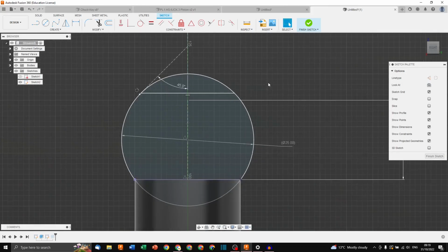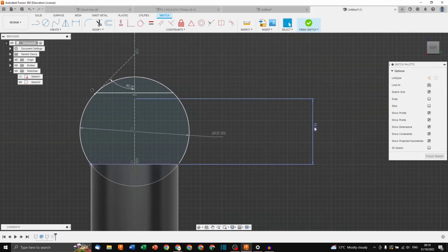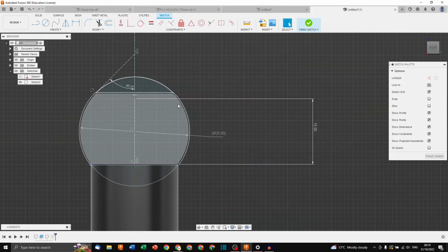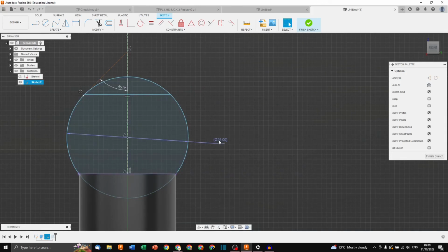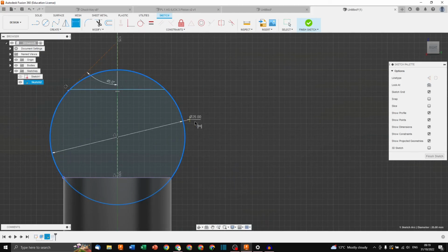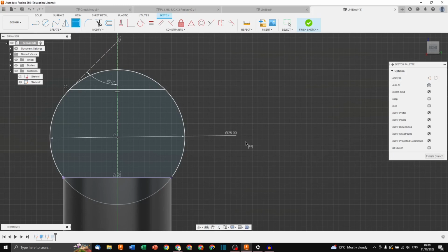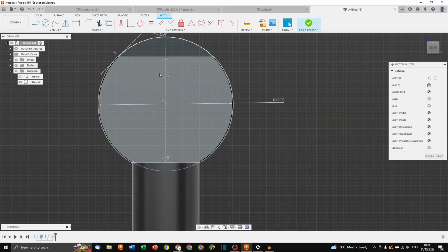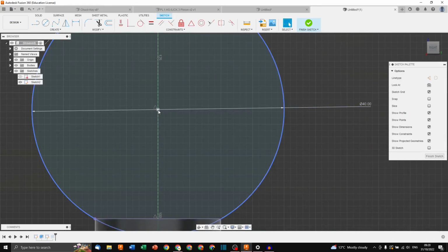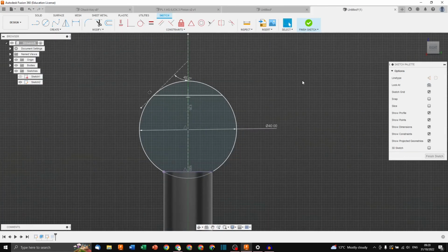Take your time, really, sit down and look at the colors, make the sketch slowly and well. Typically here, if we wanted the parameter to not be this height, but to be the diameter of the circle, because now this is a driven dimension, and that's the driving dimension, we could say that's actually not very comfortable for us. We'd rather have this be the driving dimension. We could delete this dimension. Now it's back to unconstrained. Delete this, and then add it again. And then now the one that's driving is this one. So if I change this to 30, same thing, but now you're driving by the circle and not by the line height that we decided to set the circle on the midpoint of that line. There we go.